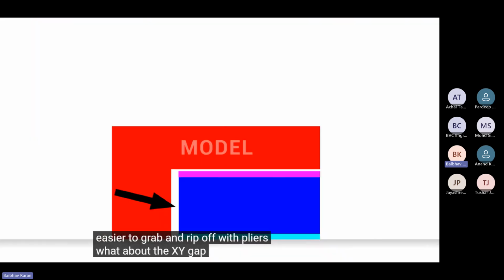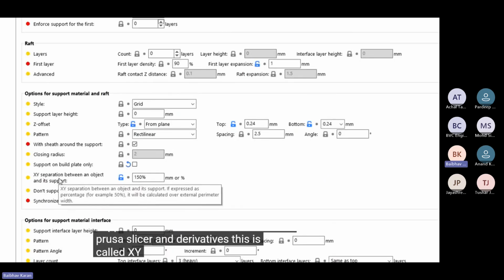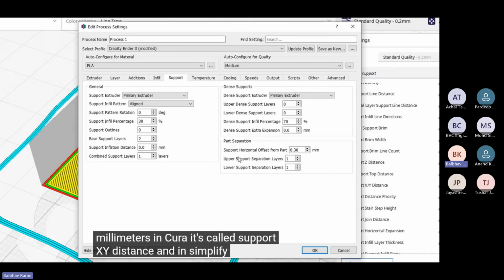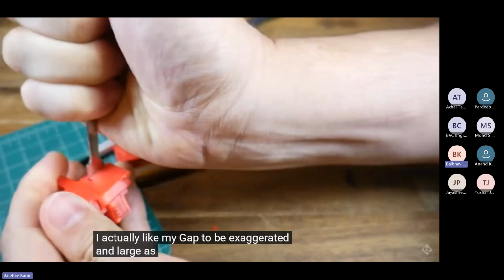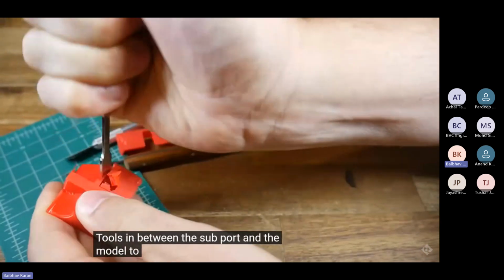What about the XY gap between the support material and our actual model? In Prusa Slicer and derivatives, this is called XY separation and can be expressed as a percentage or in millimeters. In Cura, it's called support XY distance, and in Simplify 3D, support horizontal offset from part. Here's a typical close gap that you'll see by default, but I actually like my gap to be exaggerated and large, as it gives more room to fit tools in between the support and the model to help lever it off.